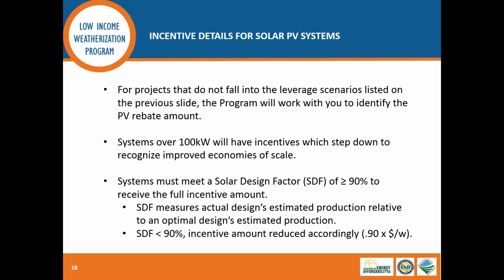the incentives will step down, so the dollars per watt will reduce, and this assumes there are improved economies of scale with larger systems like that, and the total cost is not necessarily linear. The other thing that we're looking at on the PV side is how optimal or optimized your system is. We use a tool that's offered through NREL, PVWatts, to define what the solar design factor of a project, or of an installation, is.